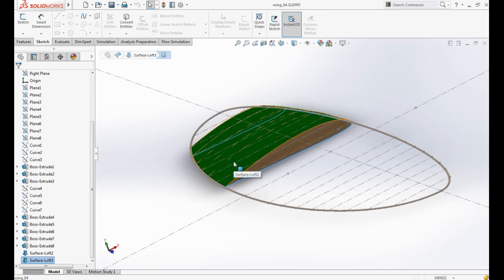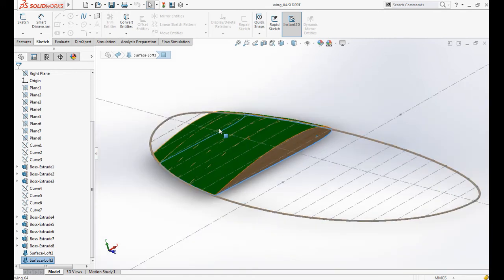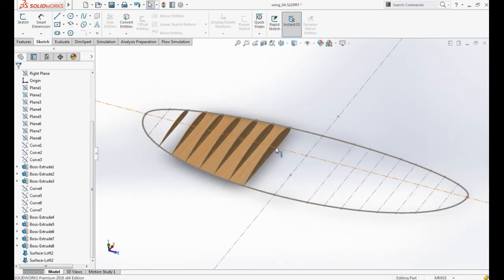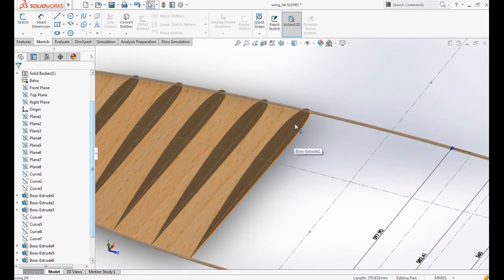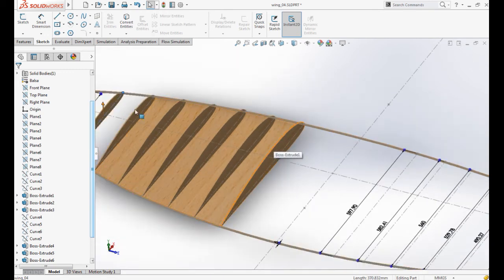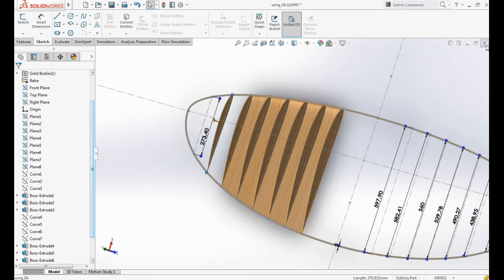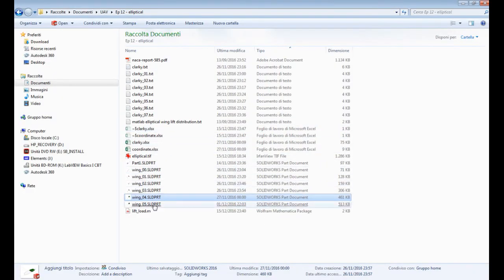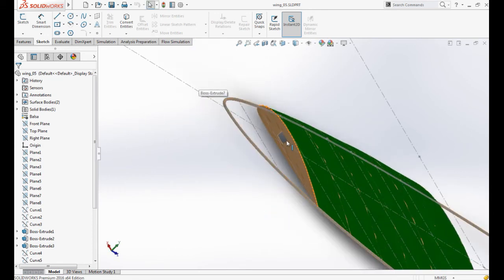If you want to make something like this, there are two ways. You can make the wing solid without the surface loft, so you will loft from this rib to this rib with just a solid wing, or you can make a 1 millimeter thickness contour or offset, and then you will loft that surface. Okay, so this is very nice, and in the end this is what you got. I left just one here to show you.